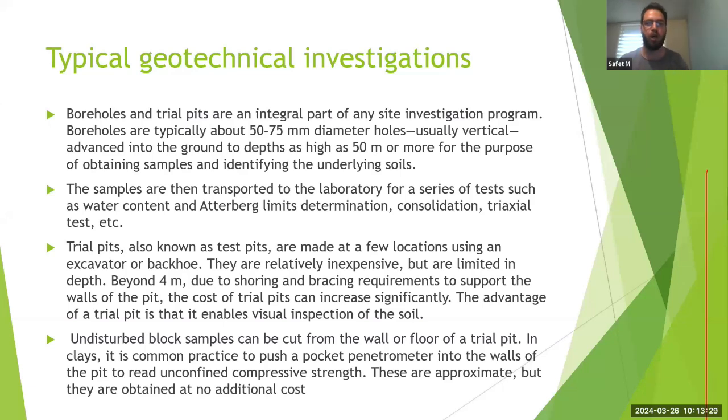So boreholes and trial pits are the most common things that you would generally use. They are an integral part of any site investigation program. Boreholes would typically be between 50 to 75 millimeters diameter, the usual vertical holes that advance in the ground to depths as high as 50 meters or more, depending on the purpose of obtaining samples and finding the underlying soils.